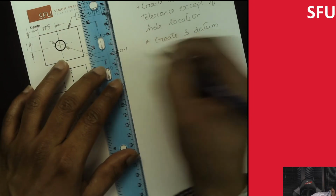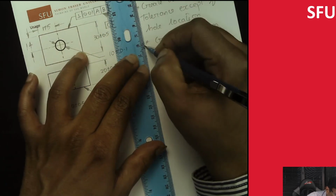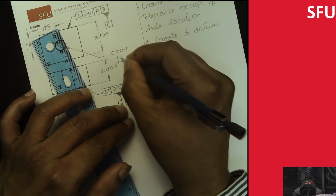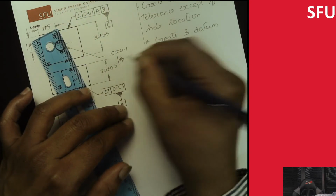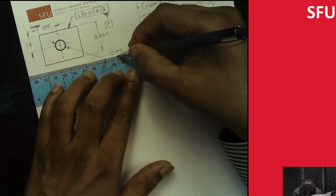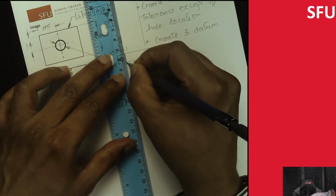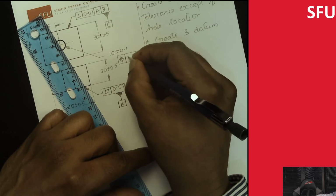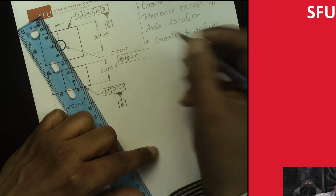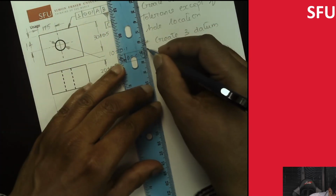And then I'm going to put my tolerance frame at the bottom. The position symbol, which is a bullseye. And then within a tolerance, we're going to go with a diameter here, 0.01, and then we're going to use the letter M. Then we're going to go ABC.